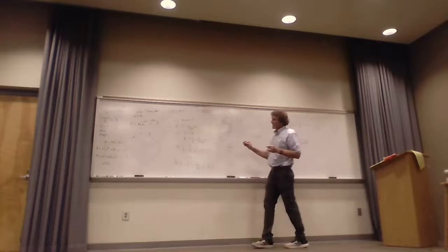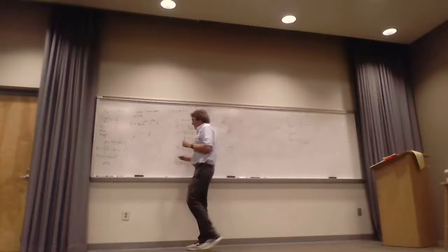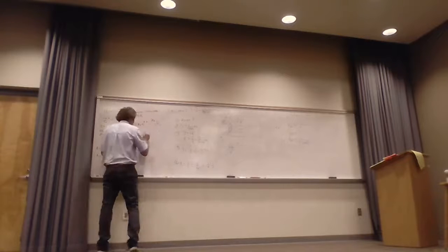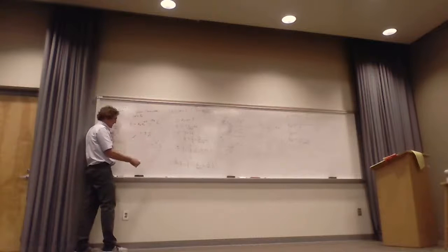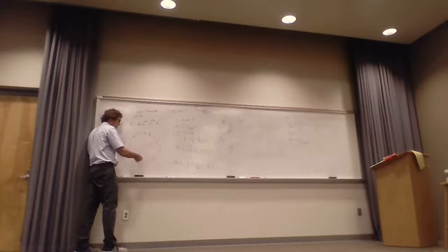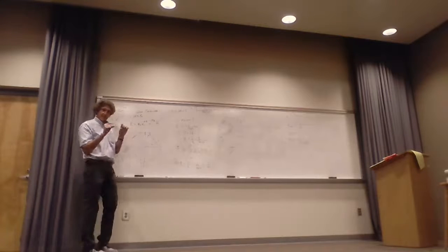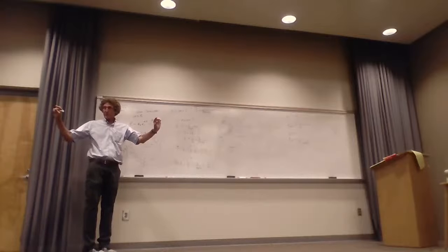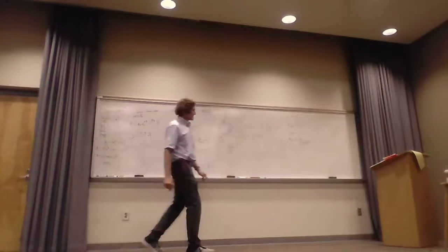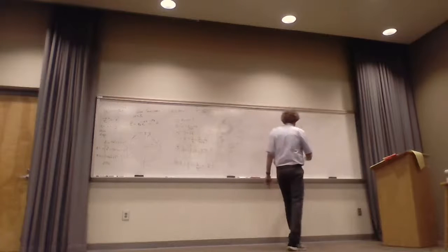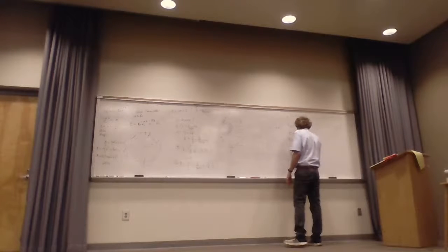Let me tell you where they get that. They say, well, if I cut this and just stretched it out, it would have a length of the perimeter, or 2 pi A, and the thickness would just be a skin depth. It's like a long, thin strip. You all follow me on that, class? All right, so that's where they get this, and that's the AC resistance for a wire.